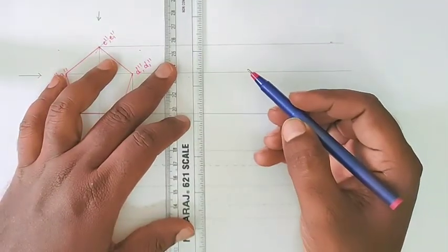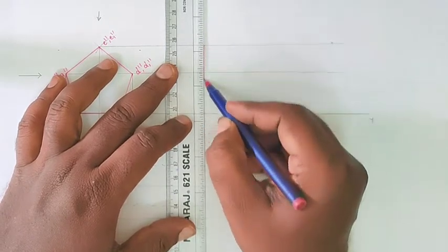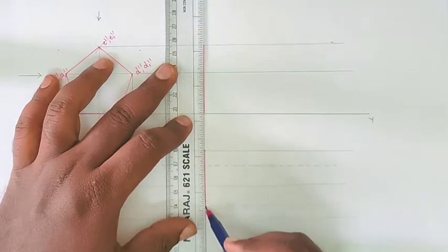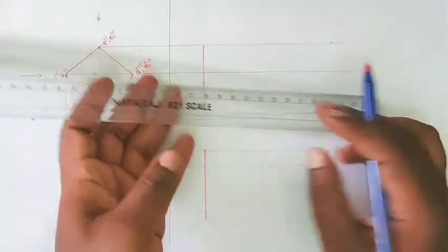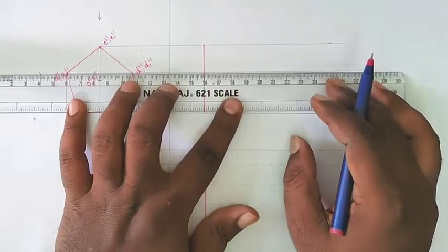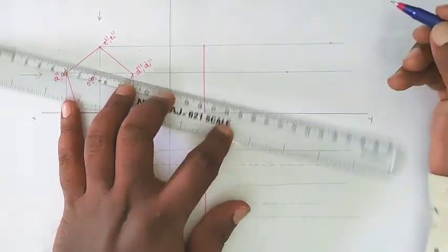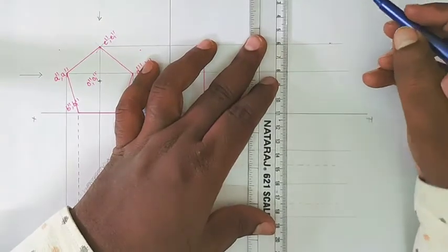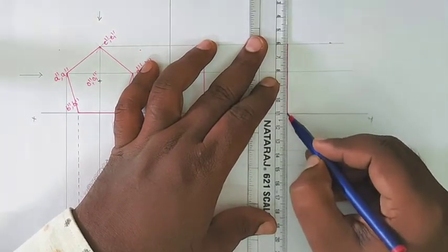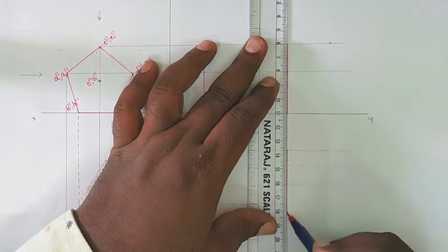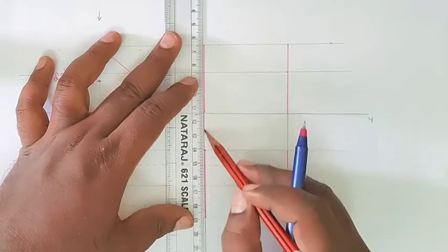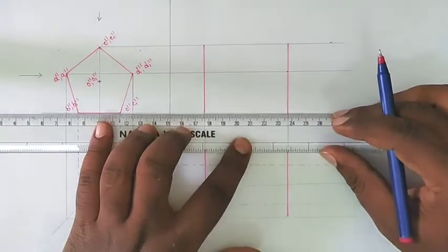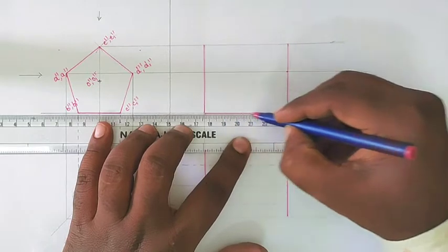Take some distance and draw one of the bases in the vertical direction like that. Take the axis side as 60 mm and we will draw the rectangle face. Take 60 mm axis side and we will draw the front view as the rectangle face, and project this in this direction also. So both the top view and front view show a rectangle face.